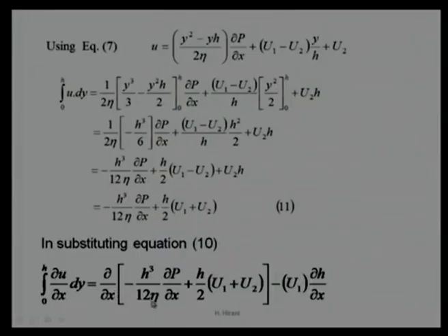We have already made the assumption that eta does not depend on x, but h may depend on x. So, we need to rearrange, and sometimes there is a possibility that u1 and u2 depend on h. Some typical examples are the rubber bearing, when there is a stretching action. That is why we use a term for u1 and u2 as a stretching term.